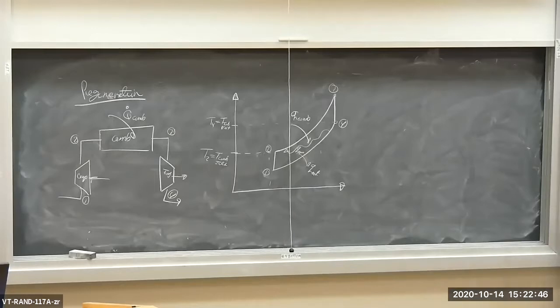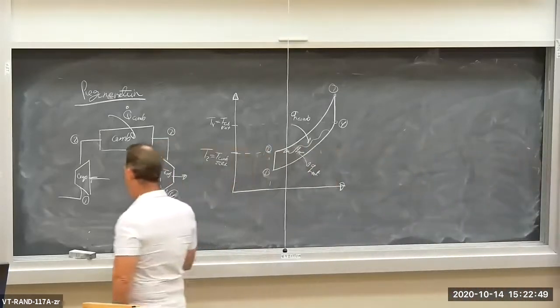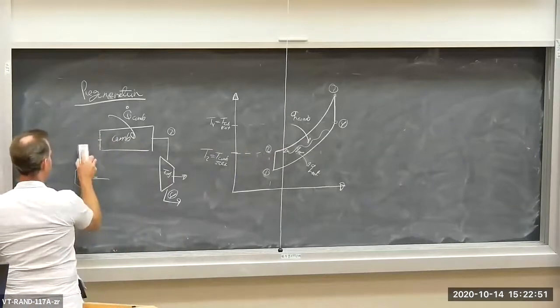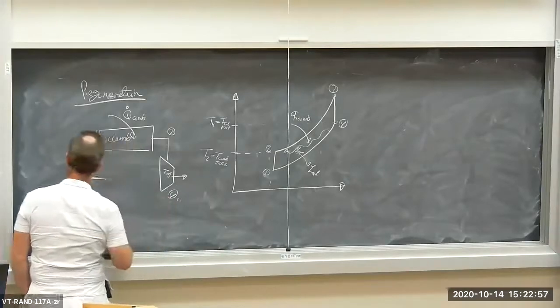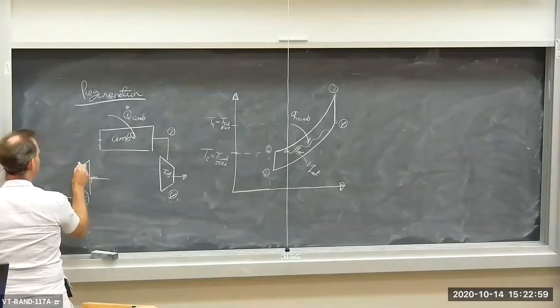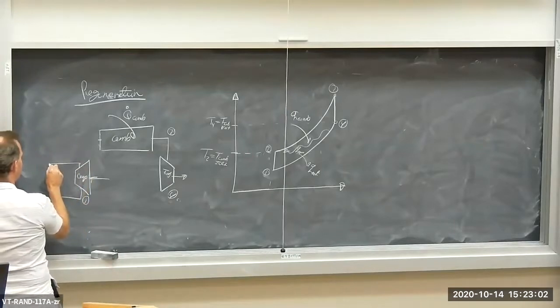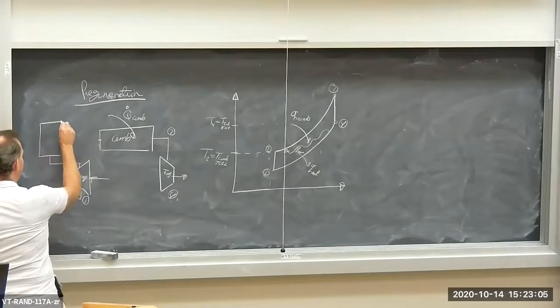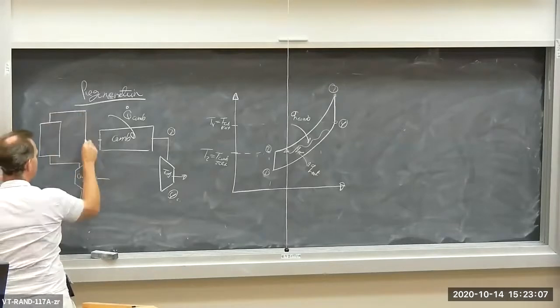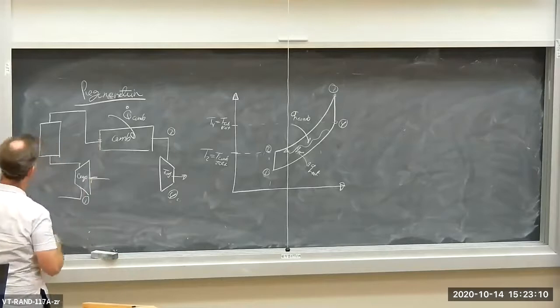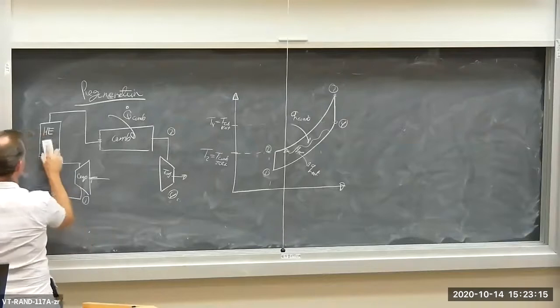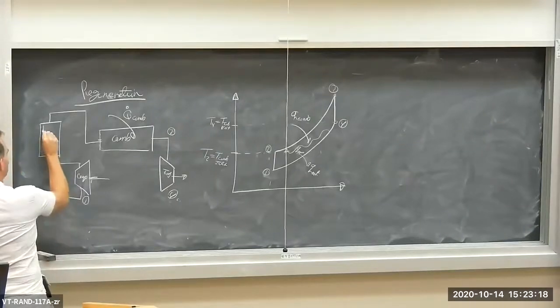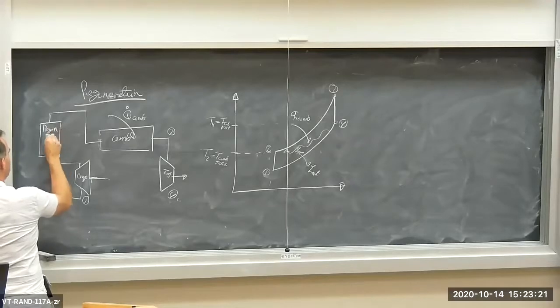Now what's a way I could do that? Instead of having this here, I can take the compressor outlet gases, air, and feed it into a heat exchanger, or if you like, a regenerator.